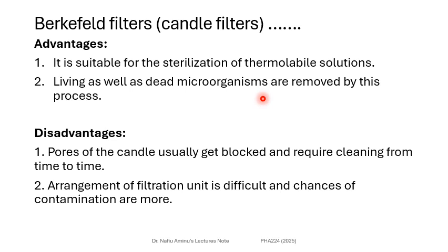The disadvantages include that the pores of candles usually get blocked and require cleaning from time to time. As I showed before, we have a procedure that we can utilize to unclog the filters, but it's one of the disadvantages because the pores are so small, so they can easily get clogged. Arrangement of the filtration units is difficult, and chances of contamination are more when you compare to other filters, because this filter is meant to be used again and again. It's not something that you can just replace, like millipore filters or membrane filters.